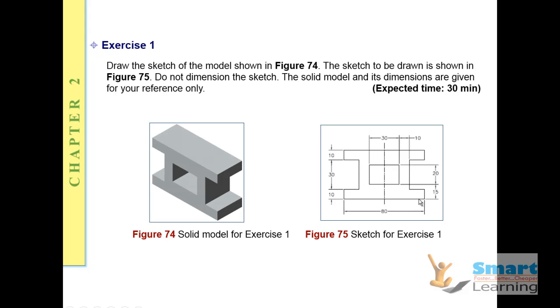You can create an outer rectangle and then create another rectangle, delete this portion and then join this, or you can directly draw this outer line and place a rectangle at the center. But when I discuss mirror and other tools, we will learn how quickly you can create this. For now don't use those tools, just use the grid and line command for capturing this, and practice how it works. So these are a couple of exercises which you can do.